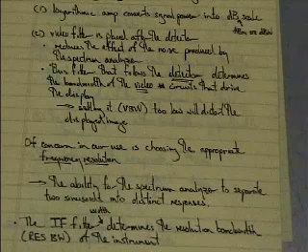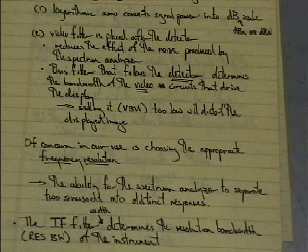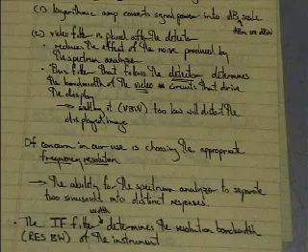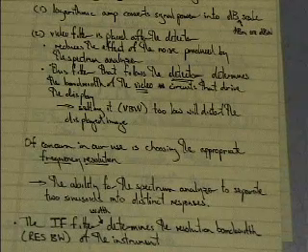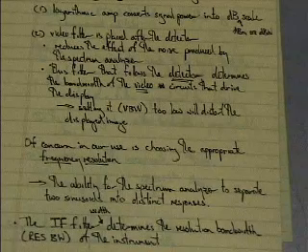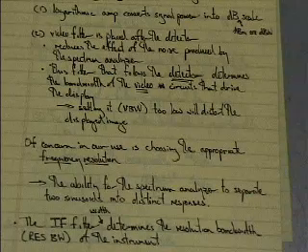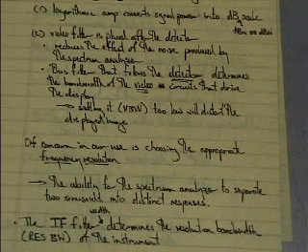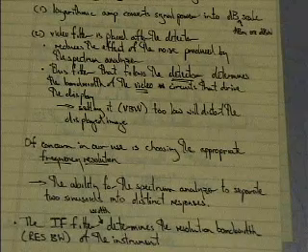I set up my spectrum analyzer to look at these two signals happening at the same time, and I would expect on my plot to see a spike at 99 megahertz and one at 100 megahertz. If I do, it means my resolution is at least as good as 1 megahertz, since these two things are 1 megahertz apart.